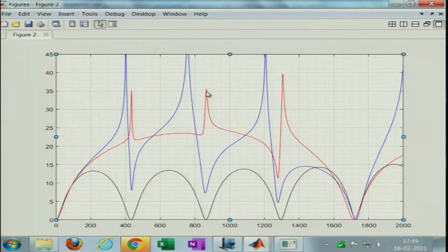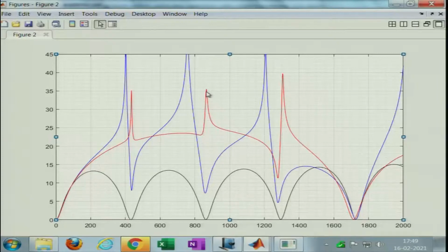Maybe we can discuss it in a different course, called numerical mode matching or analytical mode matching, where we find out the performance of such mufflers incorporating 3-dimensional effects, and then choose the length in such a manner that the 1D peak matches with a 3-dimensional peak, and then we can do all those tuning business. So basically what I am trying to say is that the acoustic performance of an ECTR will be different from an expansion chamber with extensions, and that is largely because of perforates.